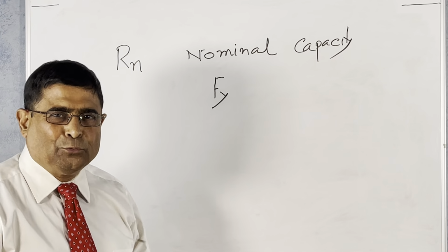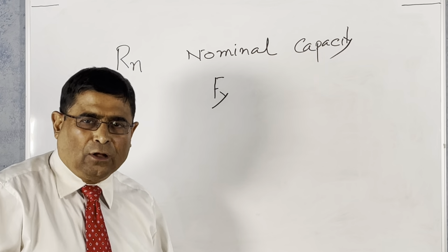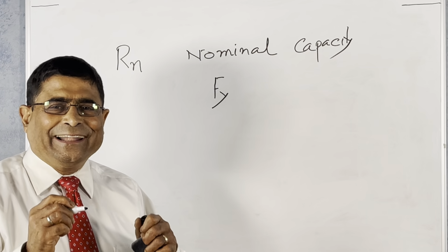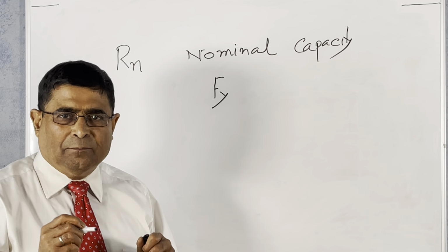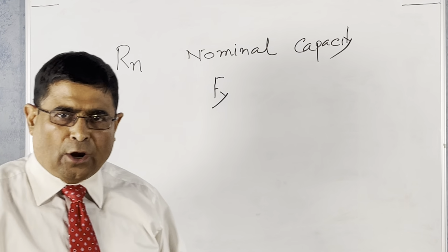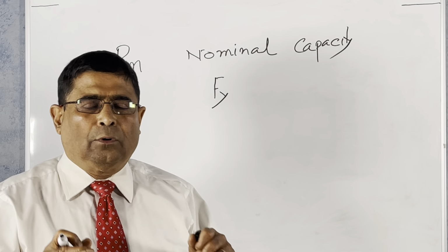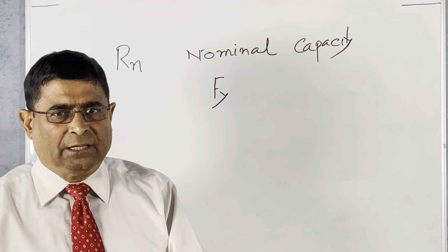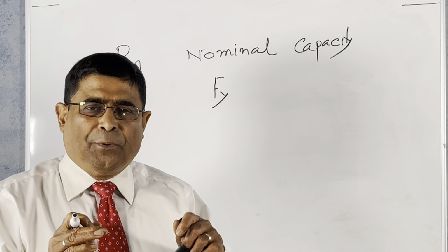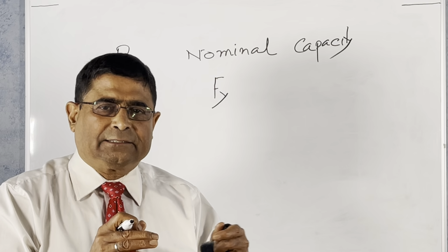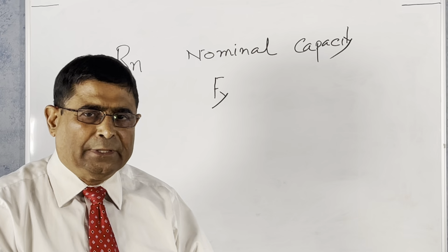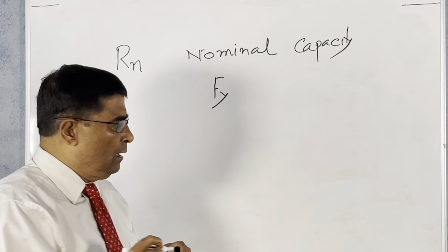You might be considering that we use concrete also as a structure, but remember, steel is also part of reinforced concrete, and in most cases it is recommended that we should design the concrete beam under-reinforced. That means the steel should attain the yield stress before the concrete does. That means before the concrete collapses, the steel should yield. Okay, that is the meaning.